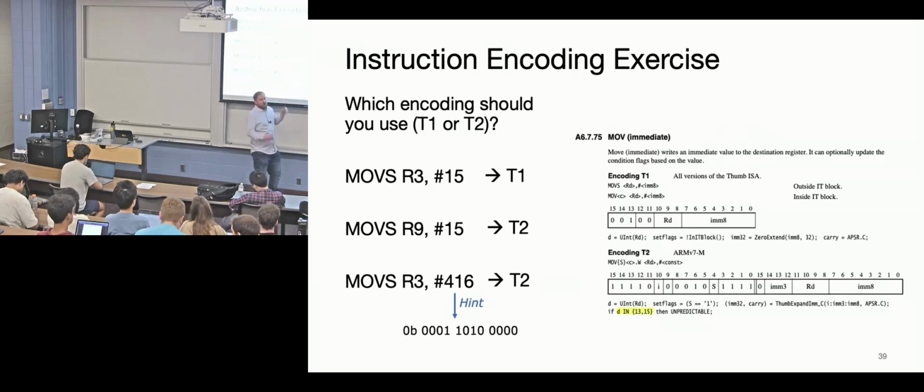Also, if you think about it, probably most computation is happening in those lower registers anyways. You're just trying to add some numbers together. Then if most of your instructions are going to be in the lower registers, just make those instructions smaller. There's no advantage to always using 32-bit instructions.